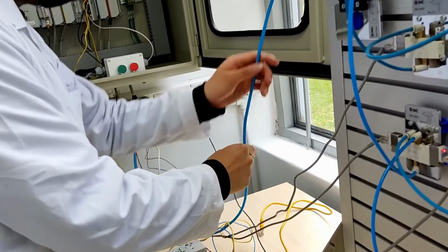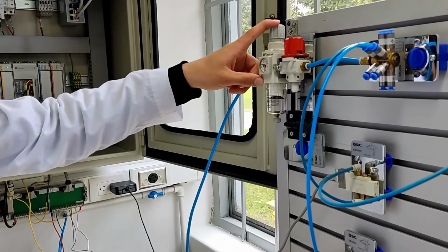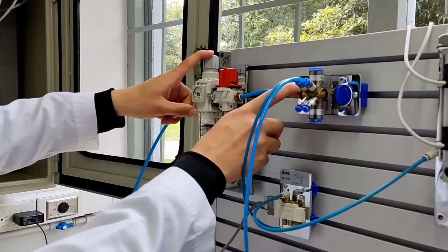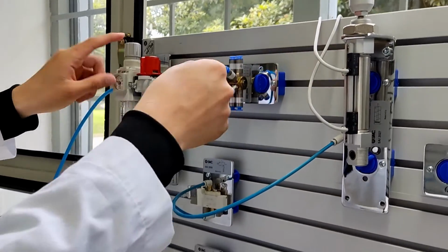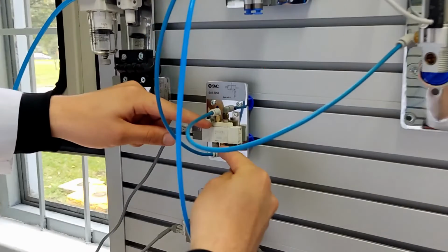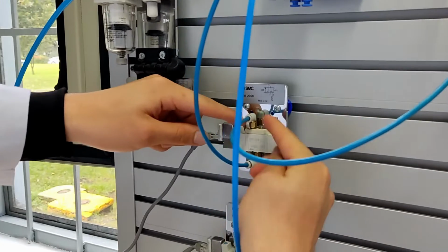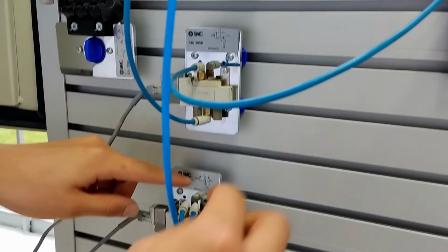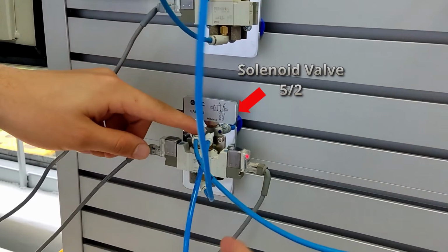Next, we have our pneumatic system that is supplied by a source with a compressor from the lab and put in our control valve source and distributed to 2 valves. The first one, a 3/2 valve with an electric actuation and a return by spring, will control our single-acting cylinder that represents the plate, and our second valve, a 5/2, that is only activated electrically and controls the double-acting cylinder that represents the pushing plate.